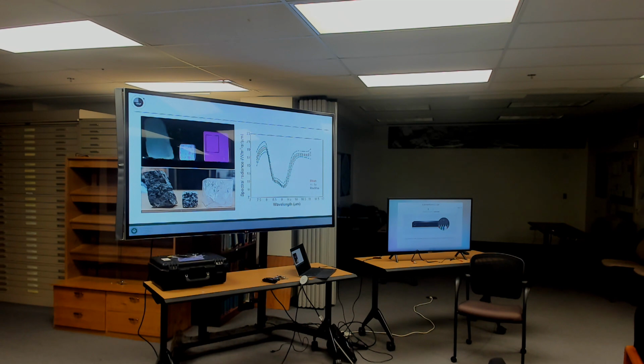And when it absorbs light, it heats up. And when it heats up, its resistivity changes. What we do is we measure the change in resistivity across that blackened metal flake. So there are some differences, we'll talk about this next week. A photon detector responds really quickly. As soon as you shine light on it, you'll get electrons being boosted from the valence to the conduction band. These detectors take a while, because you're shining heat on it, and it takes a while for it to absorb the heat, and a while for it to heat up, and a while for its resistivity to change, which means they just respond more slowly.